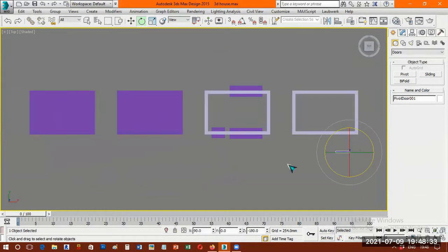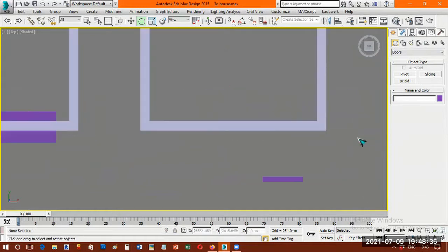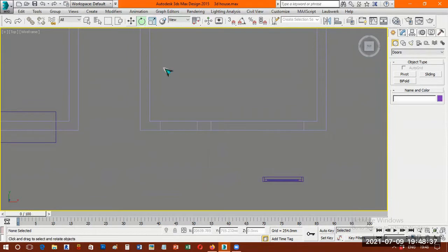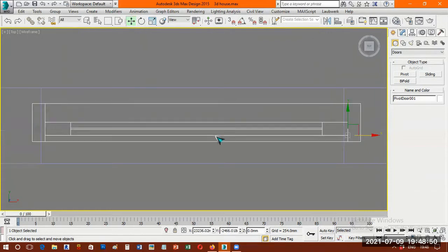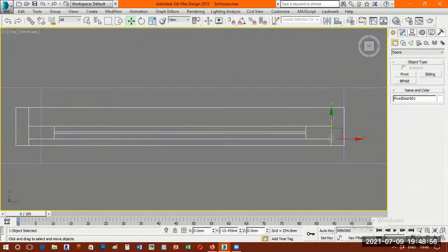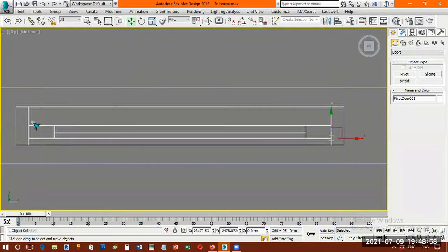Now, if I zoom, it looks like this. If I go to F3, that's wireframe mode. I select, using the move tool, click on the door, lock the y-axis and move into the wall, lock the x-axis and drag to the door area. I press Z to zoom on my keyboard to fix the location. I touch this edge here approximately. I place my location here. This is still beyond the wall.